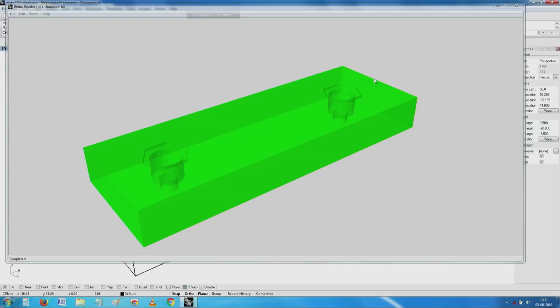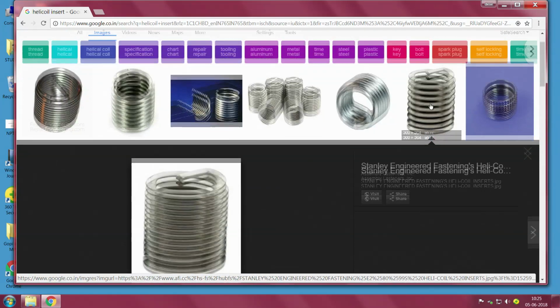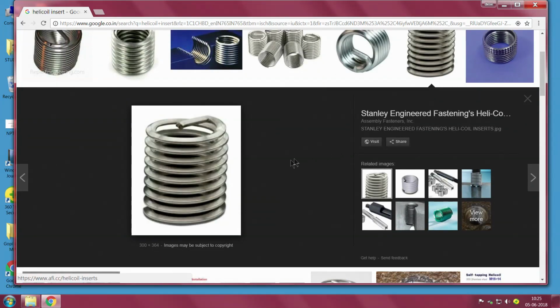I will just see if the internet is still working on the other monitor. You see, in the case of aluminum, it does not hold threads well, and even though you can tap it once, most aluminum alloys have a tendency to lose the threads after a little while. So, what is done is a helicoil is inserted into it. You have seen this?